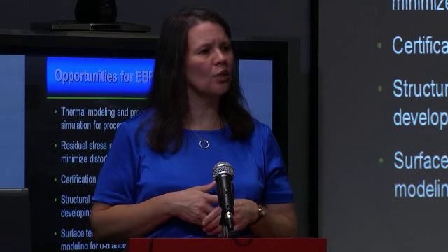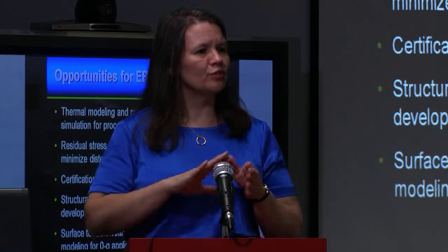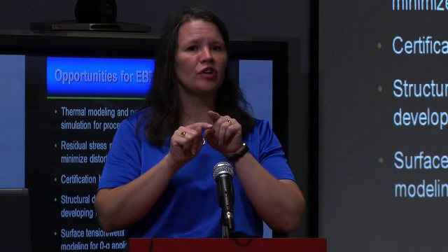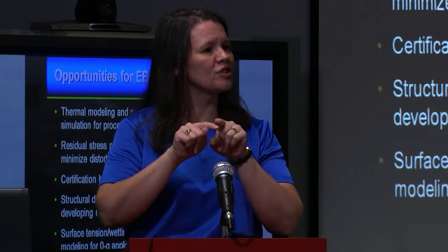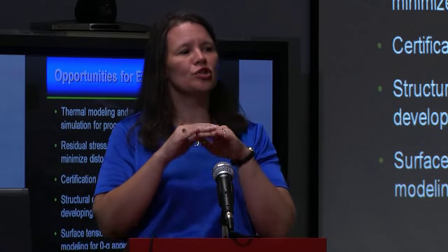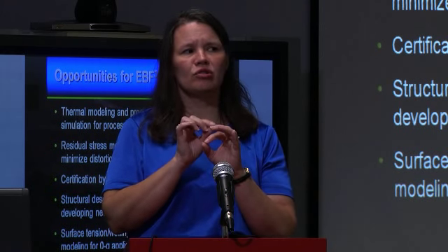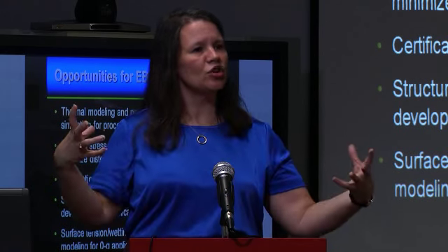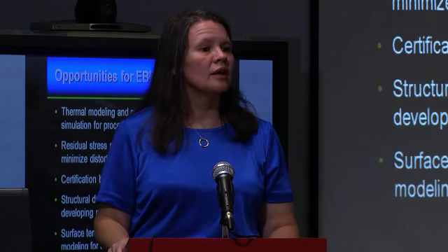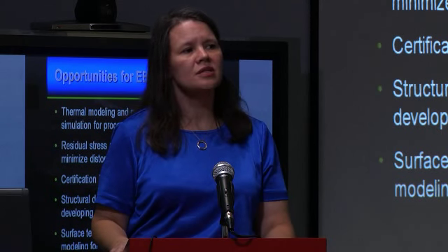Some of the things that I was showing with the stiffeners, where we can change the chemistry. We've got a multiple wire feeder, so we can change the chemistry from one wire to the next by feeding two wires at the same time at different speeds. So being able to do graded structures where I can put kind of any material with any kind of microstructure you might want at different points to try to improve the performance of the structure. Those are things, as well as if we ever get the money to build a small system to send into space. That's the other thing that we'd like.